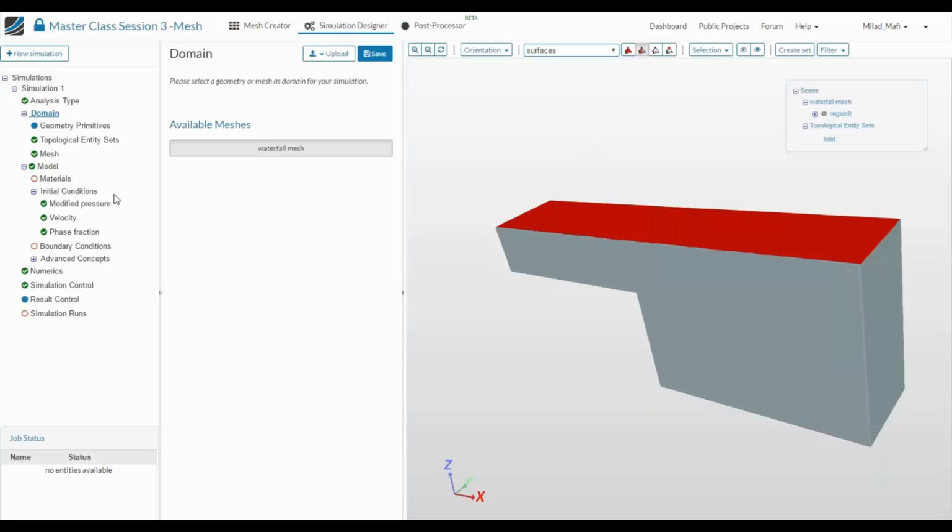And finally, you may ask yourself, why is that phase an outlet? Let's just quickly discuss this question. The reason why this is the outlet is quite easy. You should not forget there are two kinds of outlet. Something like a physical outlet where the water maybe will leave, which will not be this top phase. But an outlet can also be nothing less or more than the atmospheric pressure, which is also an outlet since we have two phases. And this is a decision depending on the actual setup you want to run.